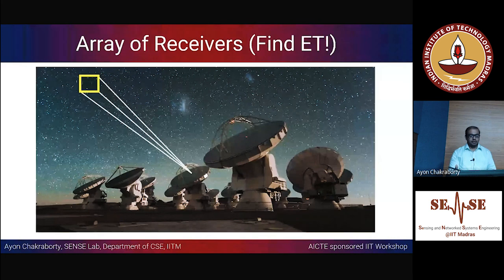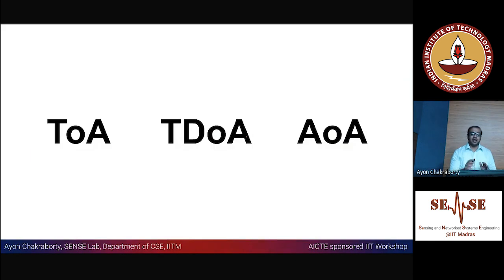Okay, so with this we have looked at most of the analytical portion of localization, that included time of arrival or time of flight, time difference of arrival, and angle of arrival, and how all this data can be obtained, and what kind of algorithms go behind them in order to build such systems. And we also looked at a real world example, using this drone and UWB, about how to engineer a real system that takes these concepts, but you need to fine tune those concepts based on your needs.